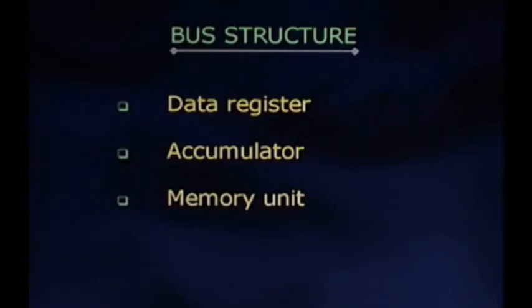It is also possible that the data read out may be transferred to one of the registers through the system bus under the control of the program. The memory write operation is the inverse of the read operation, that is, data is written into the memory at the address specified by the address register by means of the write signal.